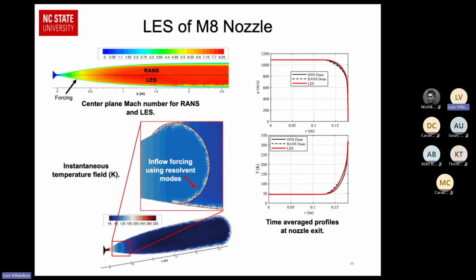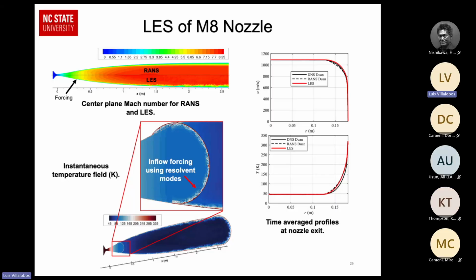But it's interesting, because anyway you're imposing it on the mean flow, and for some of these the mean flow is the problem. It settles out, but it settles out farther downstream. If you had tried to force simulate 1 or 1.5, it would have been fine. It was just some garbage near the wall behavior that we couldn't find. Really, we were trying to match more or less where we had a fine. I don't know what model he used, but he seemed to have no problem with the recycling business cleaning it all up.